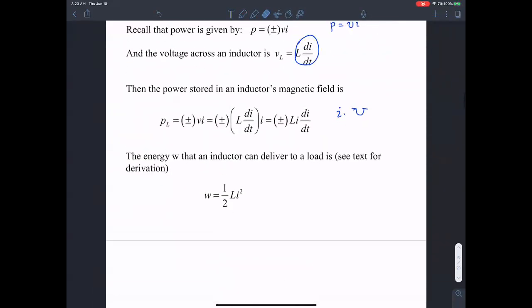So that's the idea of an inductance. Inductance is simply a winding, a wire, a coil. A changing current in an inductance sets up a voltage across it. The rate of change of this current determines the voltage across the inductance. That's the idea.